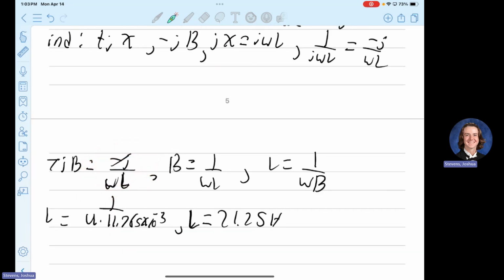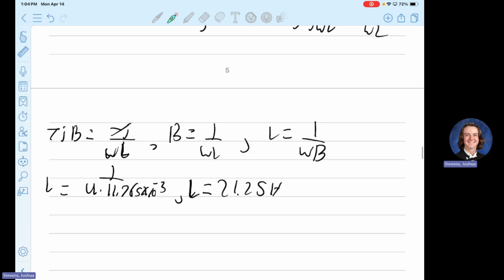Basically, the negative part of either your reactance or your susceptance tells you what component it is, and that's all it does. So we've canceled out the negative part, so you only need the absolute value of that. If you ever have a negative value in your equations to find capacitance or inductance, you're wrong. You also can't have a negative inductance, like he was saying. I think if you had that, physics would be broken. But I don't know. So we found that.